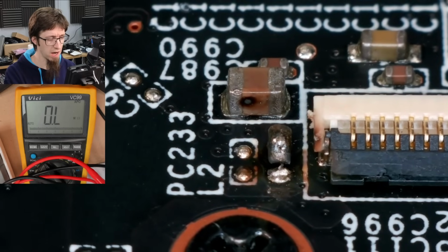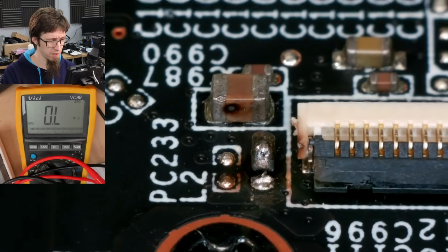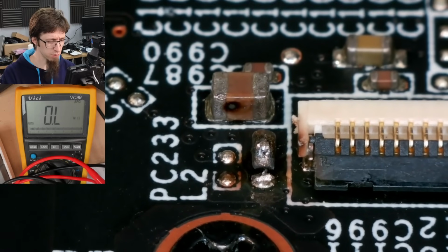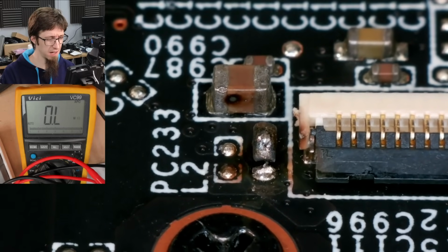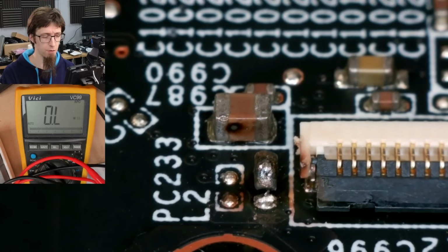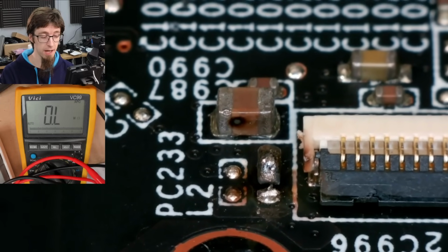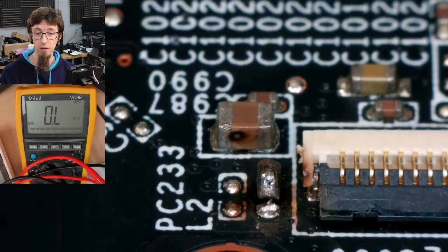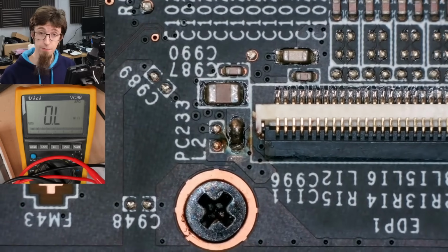But what if we looked real close for a sec? That'll do it. We've got a scorch mark on the side of the display connector. That was probably from the inductor going nuclear. But that capacitor, that's a nice hole in the side of that. That was definitely not the inductor bursting into flames that put that hole there. So this capacitor has failed and gone short circuit. That's pulled the backlight rail to ground, and then it's blown up the filter inductor. So we need a new capacitor and a new filter inductor.